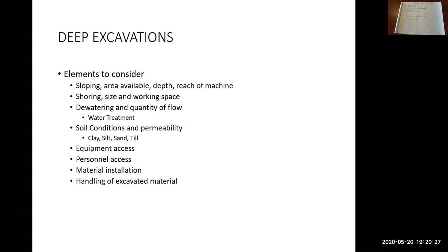So pick the excavator up with a crane and lower it down into the hole. So that machine, the excavator in the hole, would dig out kind of the center portion of the hole and pass that excavated material over to the side where the excavator that's on the top can reach it and load it out into the trucks. So you may need more than one excavator to dig deep holes. You regularly do need more than one, sometimes two or three.